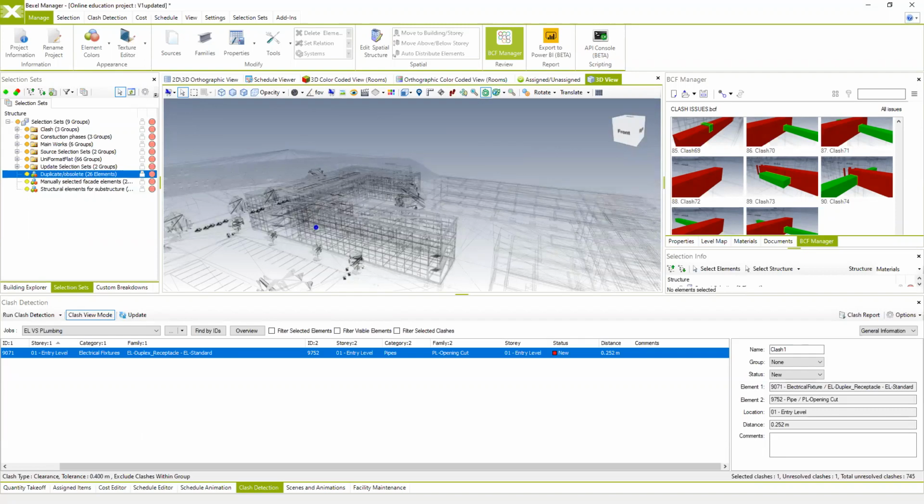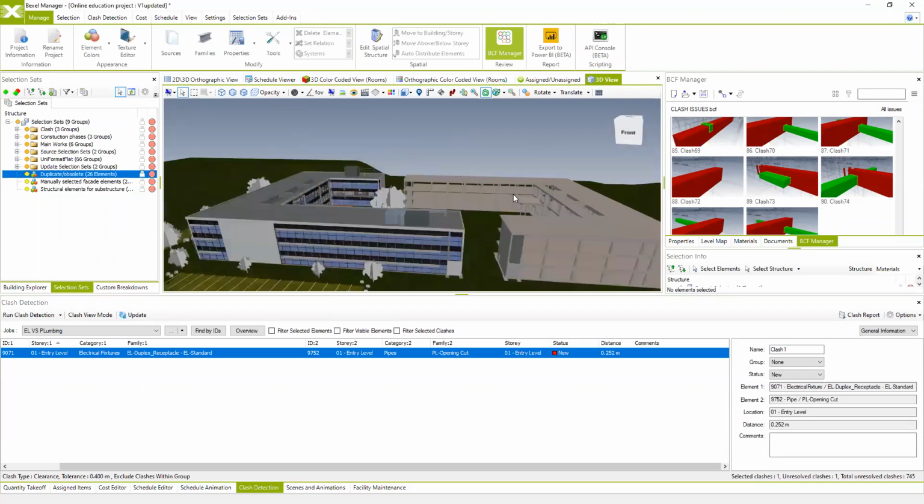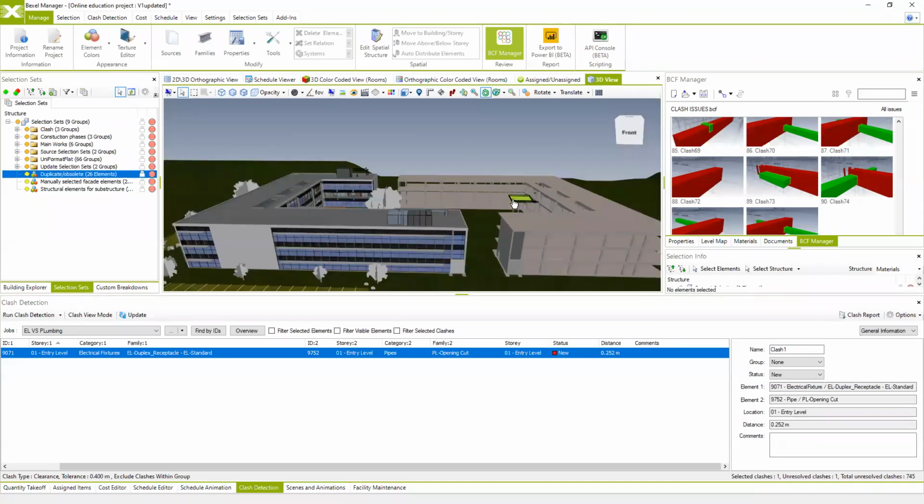So no more questions regarding clash detection. So I think it's clear. Then we can continue with the quantity takeoff. So the next thing, which is actually coming up in the BIM analysis processes, is that you want to calculate your quantities based on the available BIM model, and then according to the available quantities, you can further quantify the expenses and also create some cost estimates and similar things.